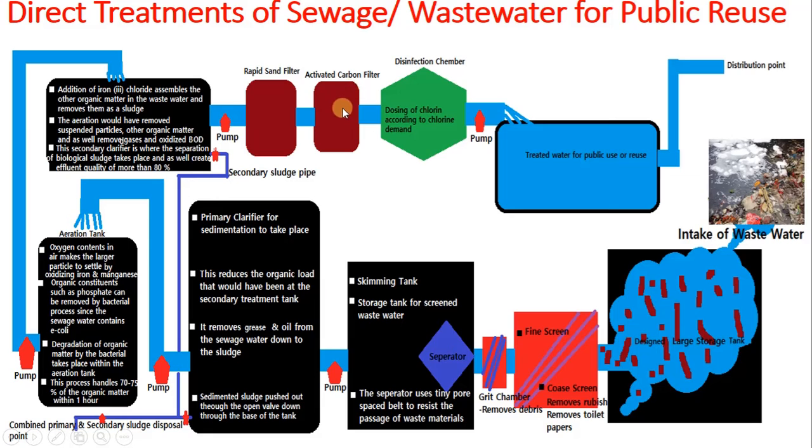After the activated carbon performs its activities, the water will flow into this disinfection chamber. In this disinfection chamber, we prefer chlorine to be used as the disinfectant. The reason is that if ozone is used here, any slightest exposure will turn O3 to O2, which will make favorable conditions for growth to come up.